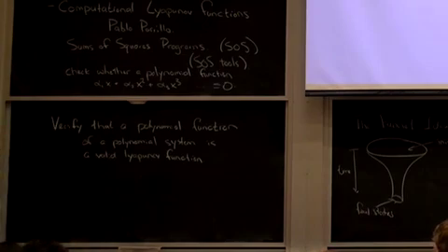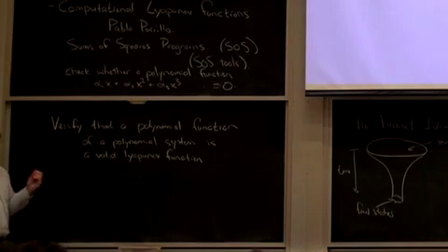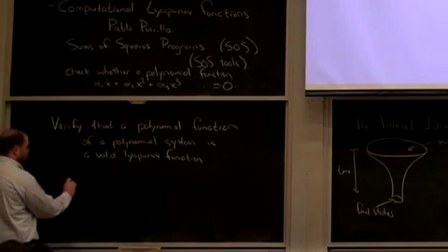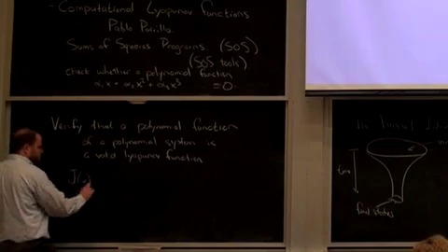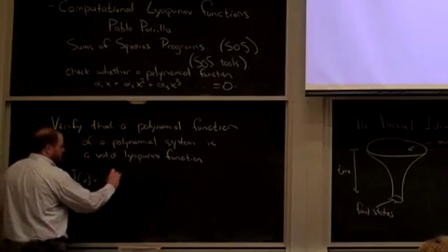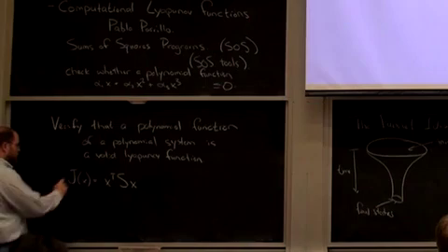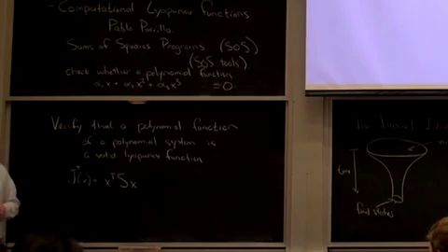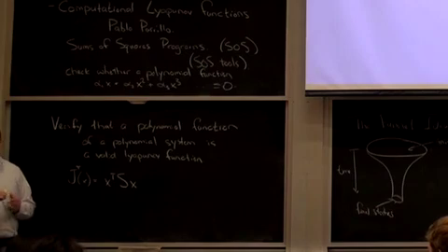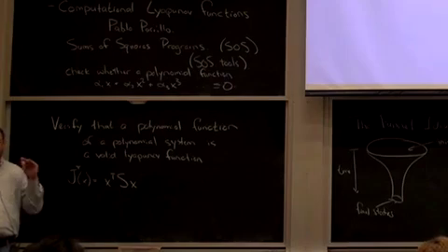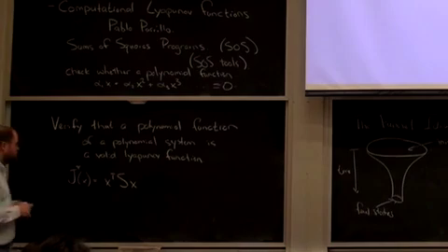Okay? So suddenly, it turns out that for the LQR systems, remember our value function, let's just think of the LTI LQR. The value function turns out to be this quadratic form, right? It's the optimal cost to go. That's a Lyapunov function. J of x for the linear system is a Lyapunov function. As I take control actions, my cost to go is only going to go down, right? You did better, otherwise it's not the optimal cost to go.